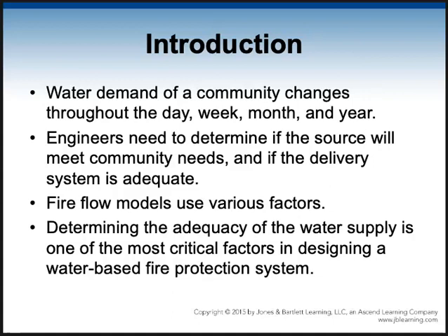Based on the fire load, they figure out how many BTUs, how many British thermal units of heat that is going to put off. Then, based on that, they know how much water it takes to absorb the different BTUs, because water has a fantastic ability to absorb heat. So how much water will it take to put out that fire? That's what they call fire flow.